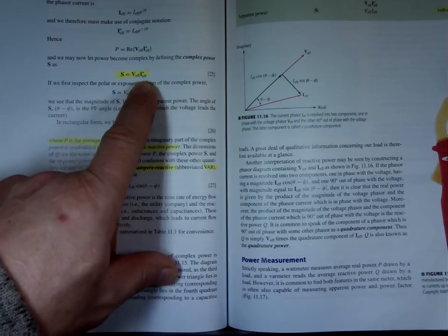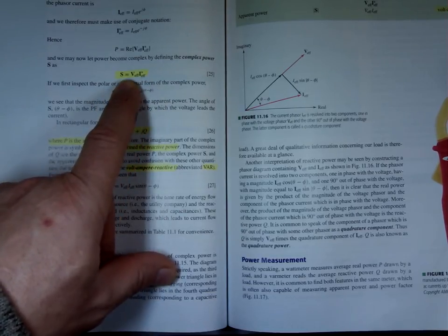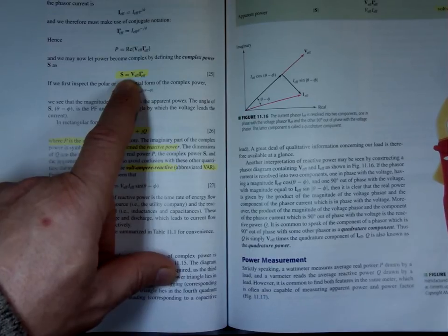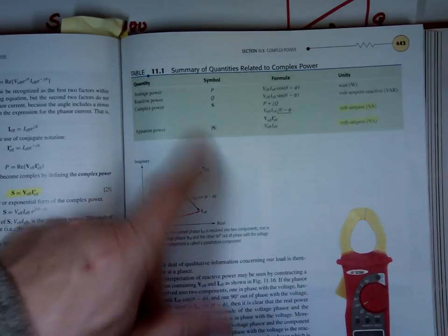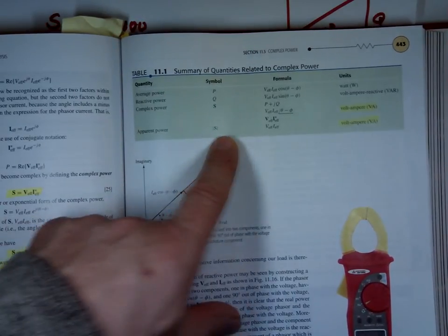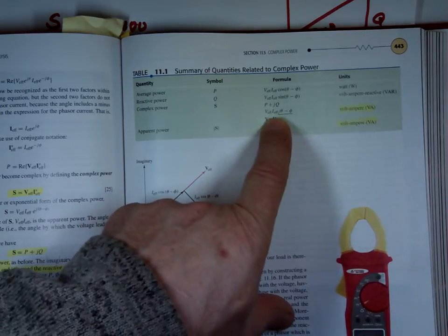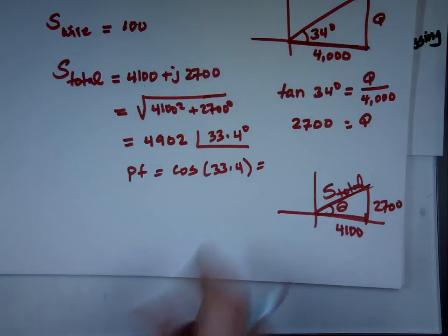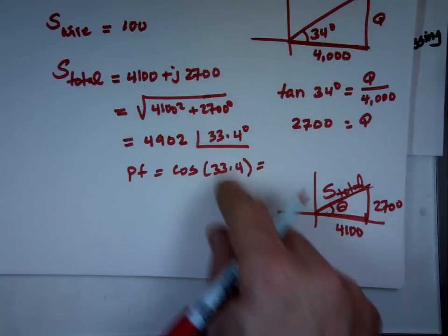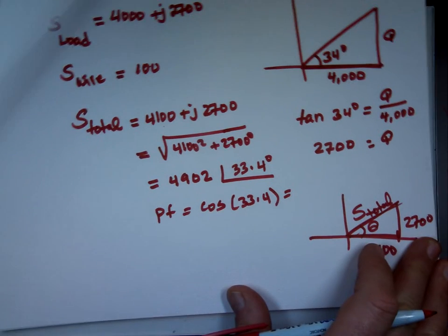So you can figure out what the value is. The magnitude of that, if you just want the magnitude, that's apparent power, the absolute value of that. Volts, amps. So V effective, I effective, theta, that's the complex power. Well, if my voltage has 400 angle 0, and this is roughly, we said 34 degrees, right? So I know the complex power now.